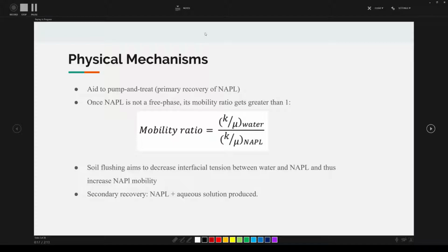The contaminant is trapped in the soil between the soil particles with strong interfacial surface tension forces, and the flushing solution being injected into the contaminated site is for reducing the surface tension, and will recombine them into the solution or dissolve them into the flushing solution so that we can extract the solution with the contaminants and then treat them.